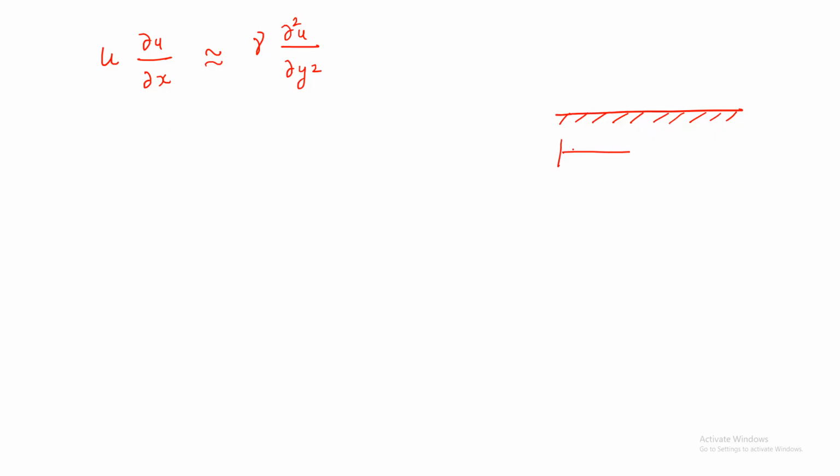Right? So let's use the boundary layer equation, in which we will just consider only the convective term u ∂u/∂x, and we will relate the dimensions of the convective term with the viscous term, which is nu ∂²u/∂y². Okay, so let us consider the flat plate boundary layer, which is the simplest case for solving this problem.